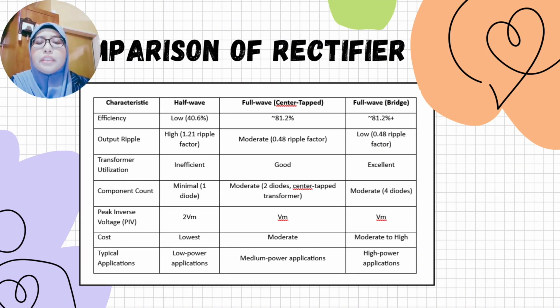Here is a comparison of rectifiers between half wave and full wave. For efficiency, of course, full wave is more efficient than half wave. For transformer utilization, of course, full wave bridge is more excellent. For the cost, half wave is lower than full wave.